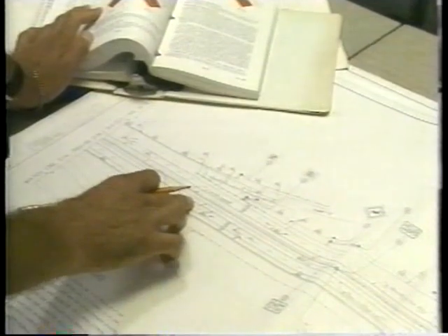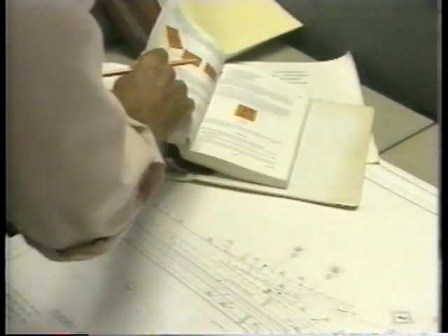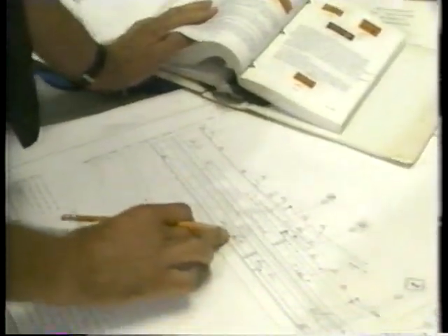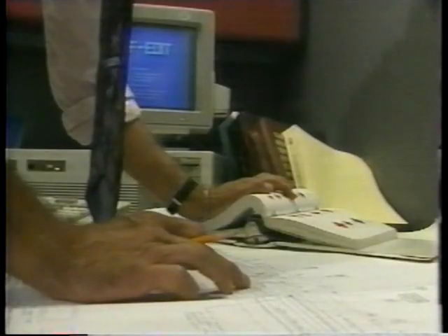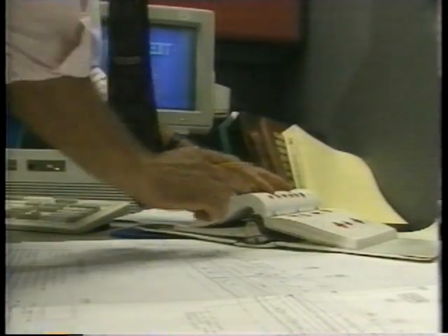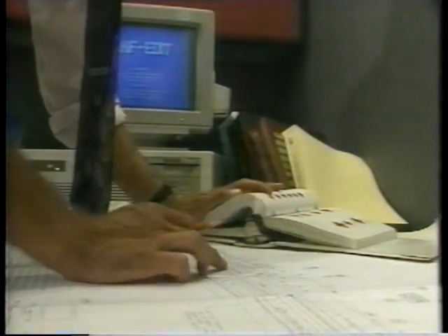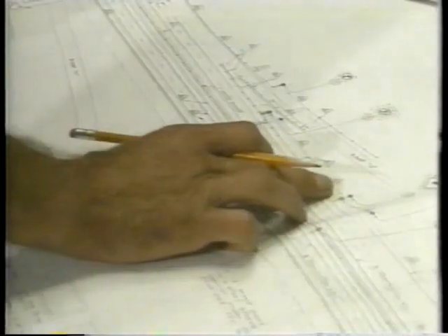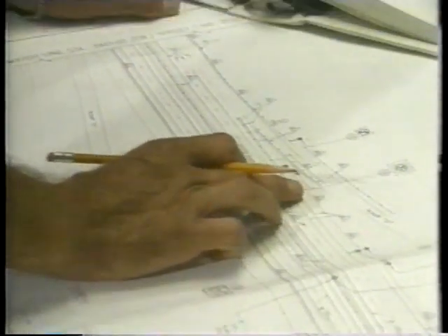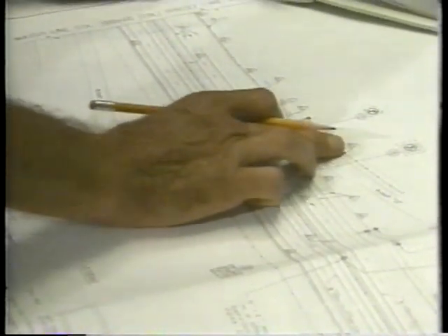That means a traffic control plan is required. The plan is a blueprint for handling traffic through the work zone. It should include traffic control strategies, staffing requirements, use of specific devices, and design of geometric features such as tapers.